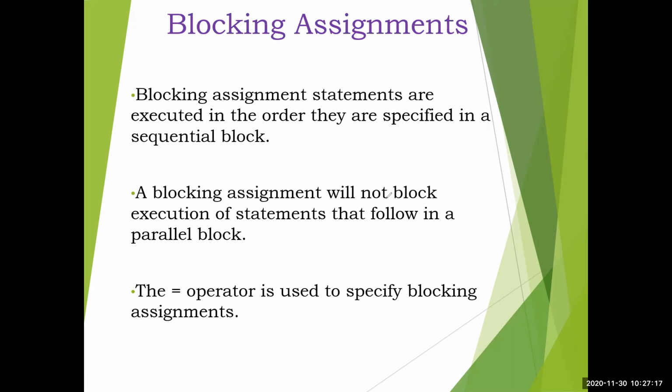A blocking assignment will not block execution of statements that follow in a parallel block. This sequential block and parallel block concept we'll take up in the end. If it is written in a sequential block, then it will execute in order. The same blocking assignments, if they are written inside a parallel block, will not work like this; they will not block. The equal to operator is used to specify blocking assignments. This is what I told you. This is the operator used to specify blocking assignments.